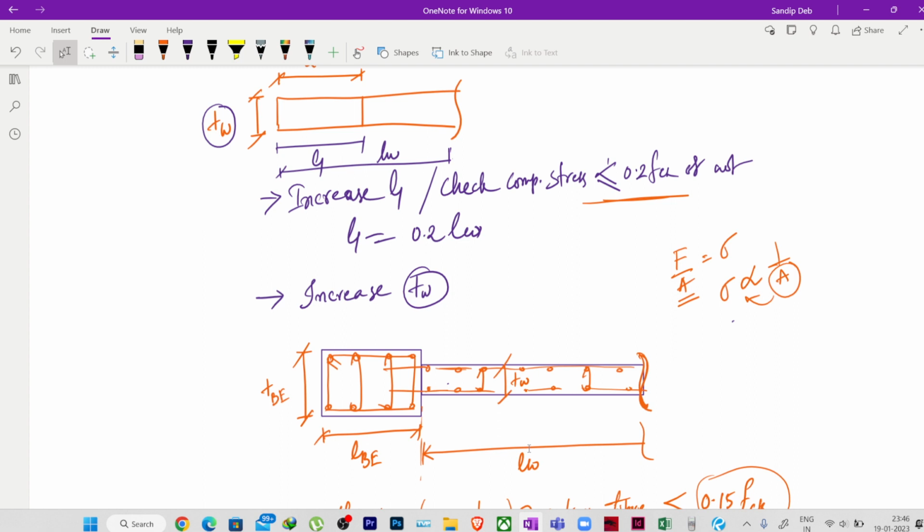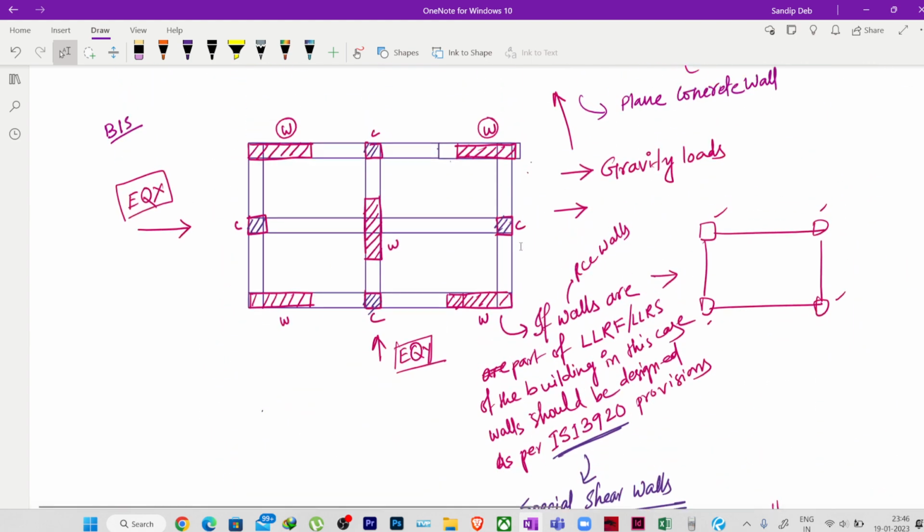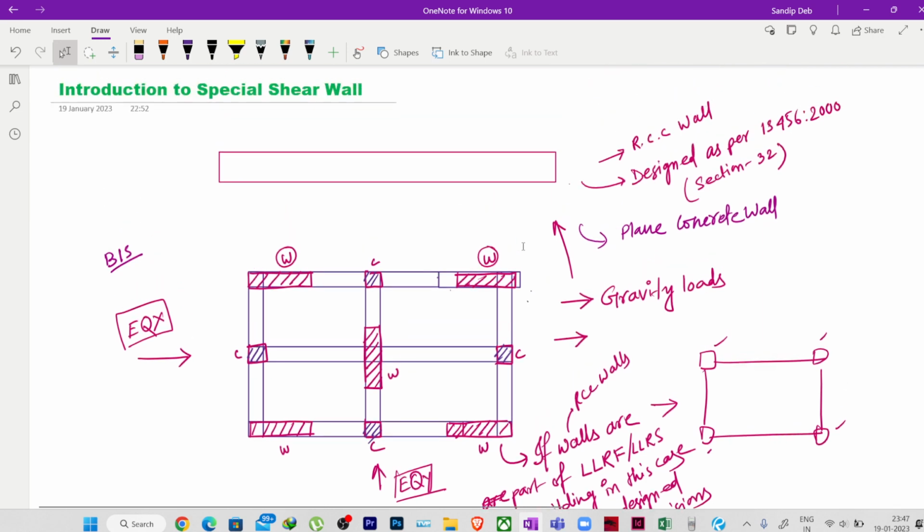Some of the walls are shear walls, some are plain concrete walls, some are brick walls. This is also seen. Okay, so Mivan is just a formwork. You can have only your beam, column and slab cast with Mivan formwork, and all the remaining walls made up of brick, or you can use the Mivan formwork for casting your plain concrete walls and shear walls also. Okay, so it's not our topic, but I have discussed it, as many people ask how to design the Mivan walls.